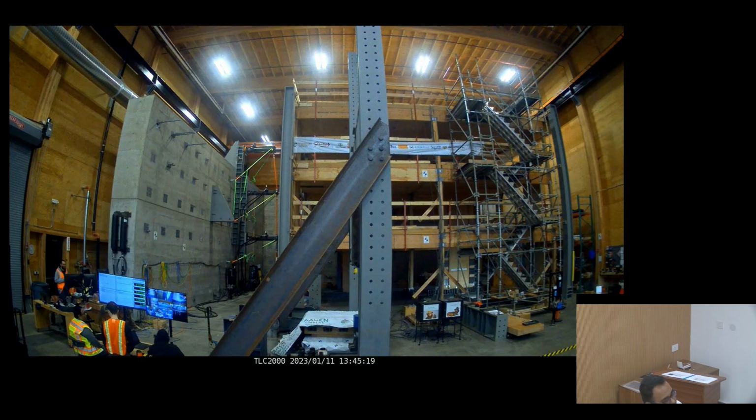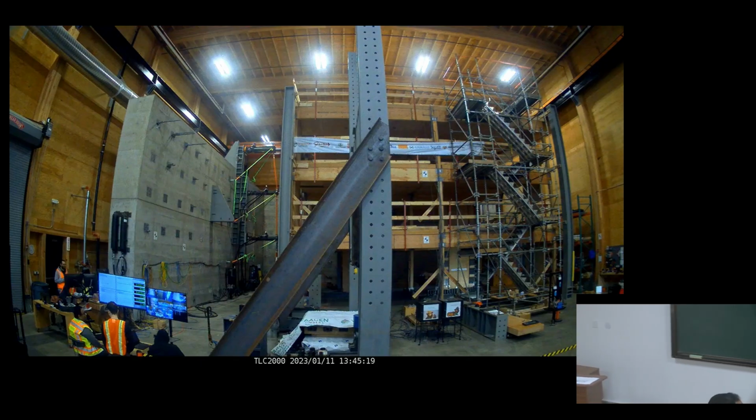Here's the building. This is a time lapse. This test took 2 days to do. This is a shear wall, one portion of the L-shaped shear wall. The actuators are connected here, 1, 2, 3, and then there's a staircase that goes up and down, but the building will move back and forth. It's pretty similar to the lab downstairs, but this is designed only for timber, so your reaction wall is a little thin.